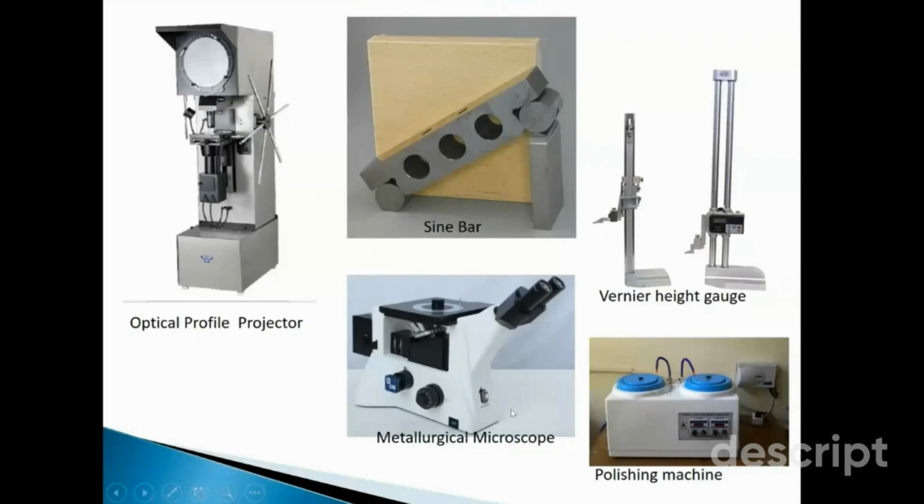We have this very sophisticated metallurgical microscope. This is called an inverted metallurgical microscope, and it is different from what you have seen in your physics or chemistry lab, which was called the upright microscope. In an upright microscope, your measuring lens is at the top of your workpiece, while in this case, you see there, this is a turret which has different lenses of different magnification, and from the bottom it is grabbing the image. This is our digital camera which is connected with our computer, and then we can analyze its image and microstructure under the microscope, and it is transferred into the image analysis software.